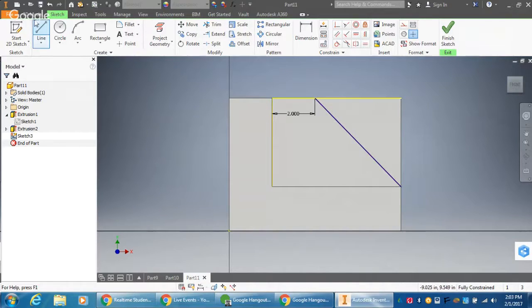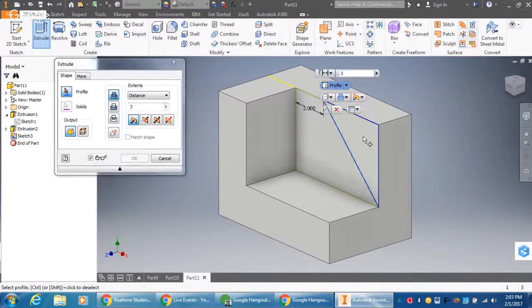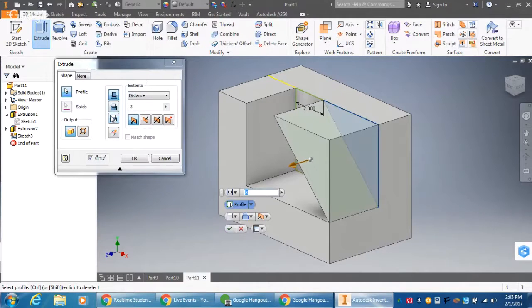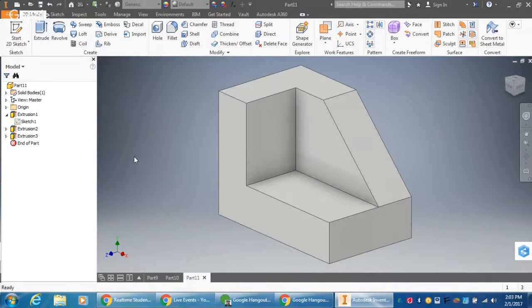All right, I'm going to go back and close this geometry the way that I want. So click and overlap that corner. And then from there, make sure I get a green dot. And now I have closed geometry that I can cut. And I want to select this profile to cut. And just cut that off. And there is part 11 done for you.